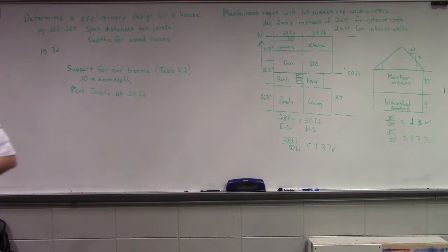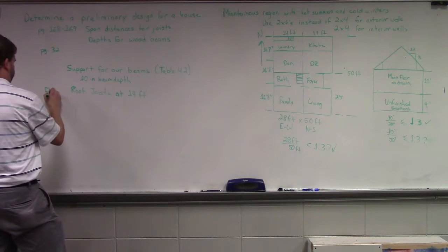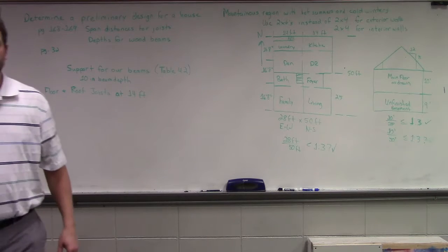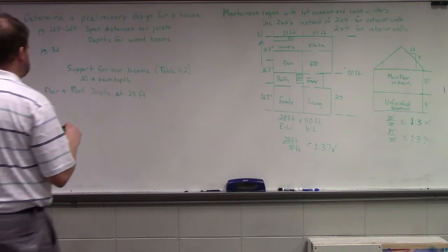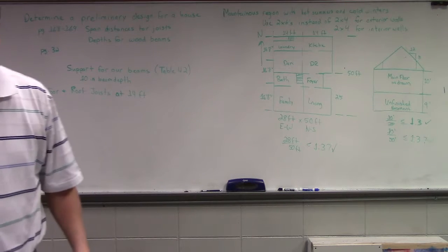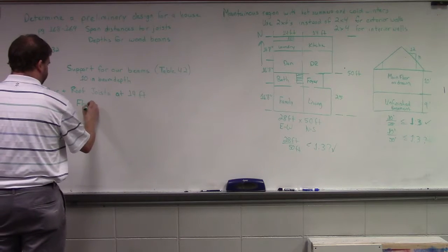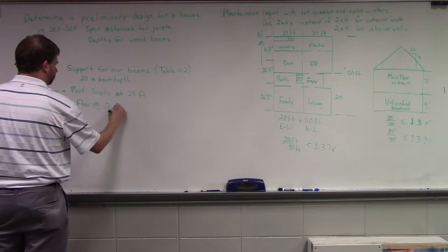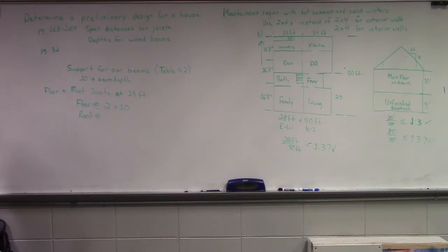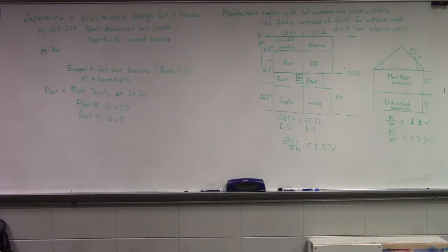And if we're setting floor and roof joists at 14 feet 10 inch. Which one? Don't you have a difference? Oh, are we doing 4.1 now? Yeah, joists are in 4.1. So what is your floor going to be sized at? 2 by 10. And the roof, 2 by 8. 2 by 8. Okay.